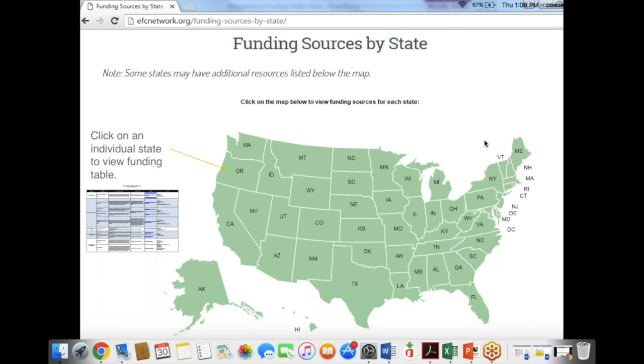We also had one very specific question that relates to one piece of an inventory: how do you determine the realistic lifespan of a piece of equipment? And that gets into that useful life question. So we always ask people to make an estimate of how much longer you think a piece of equipment, one of your assets, is going to last. And one way that people like to use is just thinking of age. And we want to be really careful using age as either the only or primary indicator of how much longer a piece of equipment is going to last, because it's really not that great of an indicator